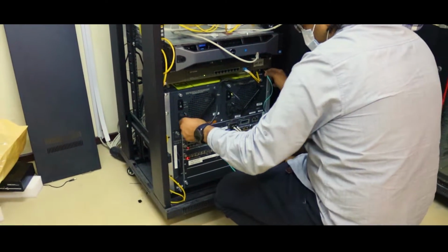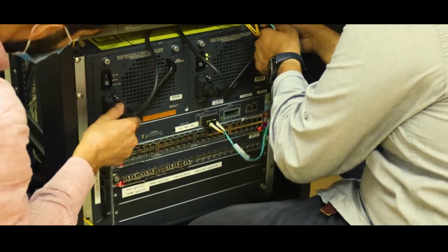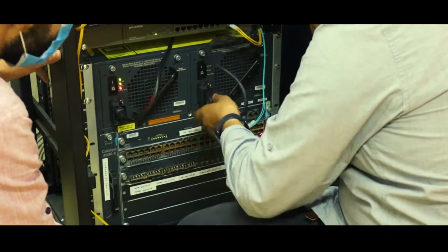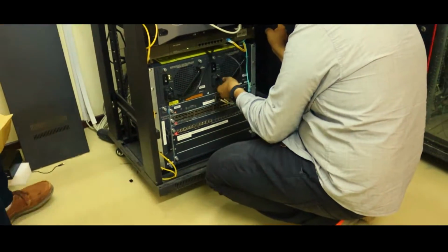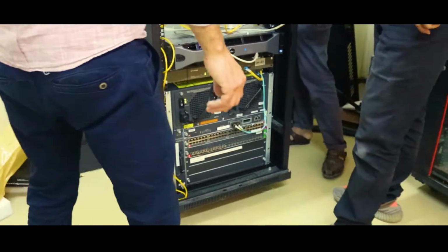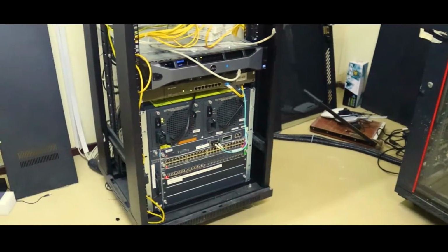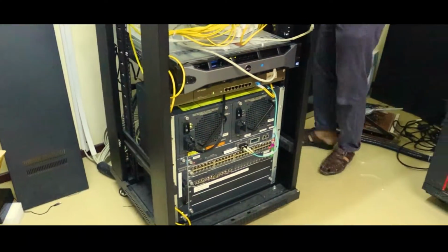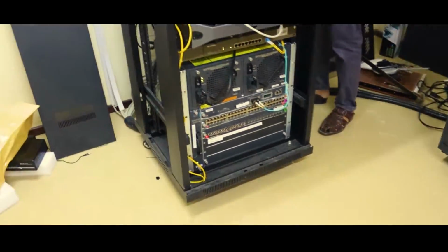It turned out that one of the power cables was not okay. I think fused maybe, or a damaged cable. I happened to check only one cable, so I switched, and yes, the cable is damaged. So we'll remove the cable, and just one is enough. Because the power supply is 2800 watts and our consumption is not that much, because we will not be using too much PoE power. I think only one access point will be powered from this module.